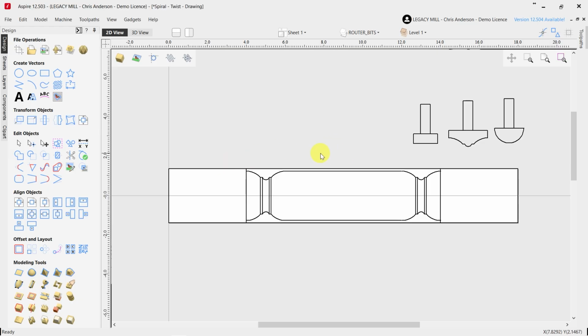And just like other spindles that we've done for the spiraling process, we have the design of the square on the end of our blank, and the center section is where it's going to be turned round, and we're going to apply the spiraling toolpath between these two cuts. So far, this has already been programmed and cut to turn this round using a surfacing cutter all the way to the end, from beginning to end in that way.